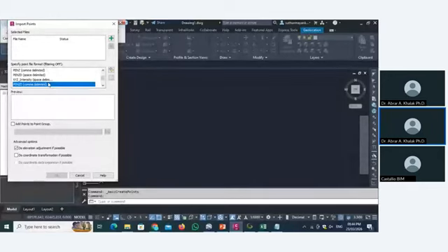So what is this PENZD? P is for point. Point means 1, 2, 3, 4, 5. Right now we are creating this file format, so don't worry, you will understand. E is easting, N is northing, Z is elevation, and D is description. Description, like if there is a point near a tree, then in the description they mention the tree, or any obstruction, that type. If it is a center line point, then they maintain that description there. Okay, so I hope you understand this point format.